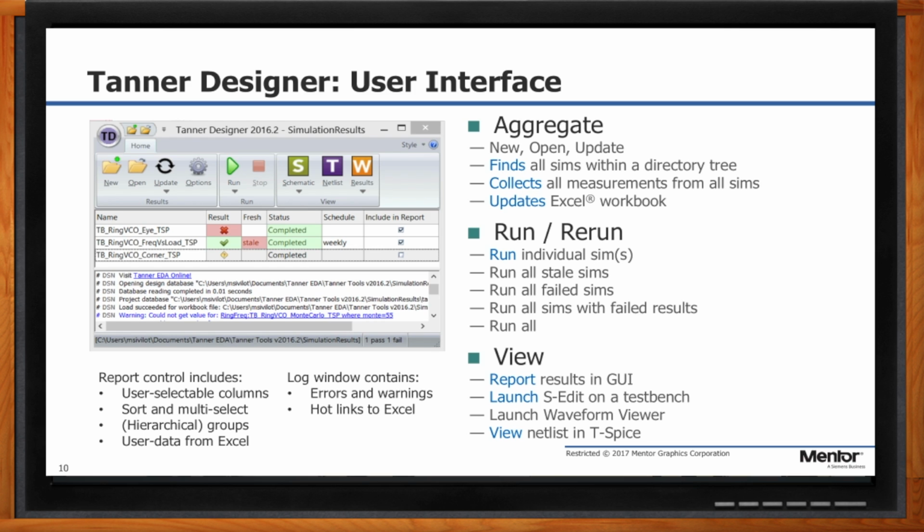You always report the results in the GUI, which is the pass-fail, but you can also launch our schematic editor on a test bench. You can launch a waveform viewer, and you can view the net list in T-Spice. So as you have hundreds or thousands, perhaps, of tests, you don't need to remember where they're all located on the disk. You can just choose the test here and click on the button, and it will navigate you to it. It's kind of a design manager in some sense.